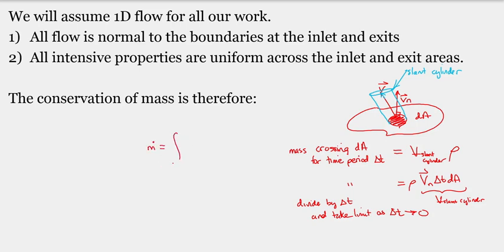And on the right-hand side, we have an integral over the total area of the density times the normal velocity component times dA. Okay. This is really important. This is a fundamental definition of the mass flow rate.